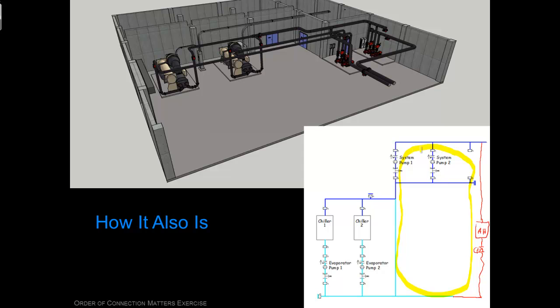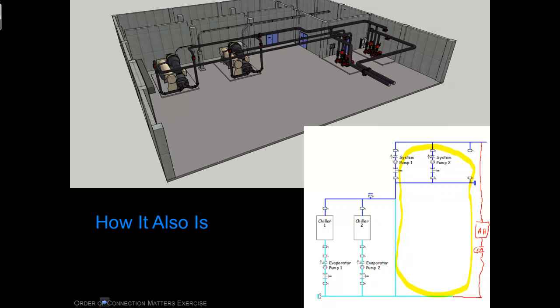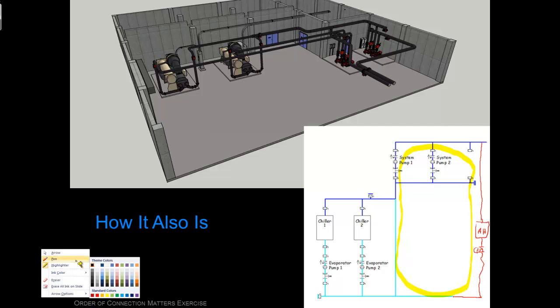The flow of these pumps, because there's two-way valves on the air handling units, is going to vary. And as these valves throttle as the load drops off, they'll basically restrict the flow. And if I didn't do anything else, if I just had pumps sitting there, no variable frequency drives, no variable speed drives, I would shove the pumps up their curve. In other words, I'd reduce their flow rate at the expense of producing more head. And that actually saves energy eventually. And I'll refer you to the pump class slides for the details of this, but I'll just make a real quick sketch because we kind of could use a pump curve for some of the things we're going to talk about anyway.